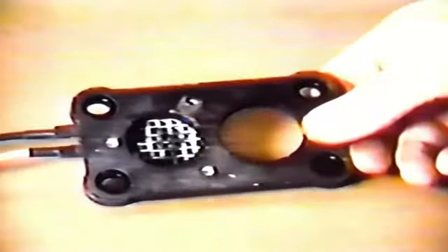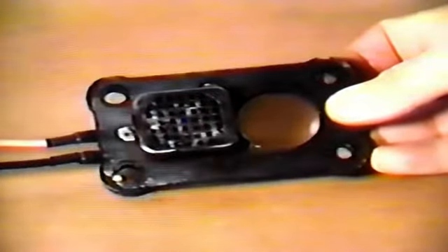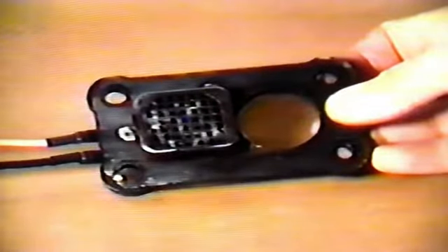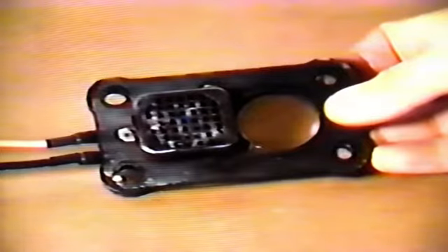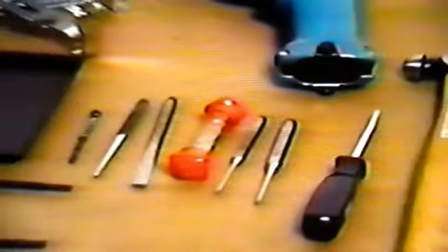If it does, thoroughly inspect it for erosion, especially the bottom side. This step is crucial because a badly eroded grid can cause serious problems in the engine if a particle of metal were to fall into it. If the grid does show signs of erosion, it's a good idea to replace it, even though it may be working properly. When the erosion check is completed, you're ready to go to work on the carb itself.